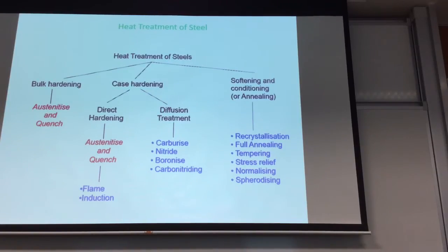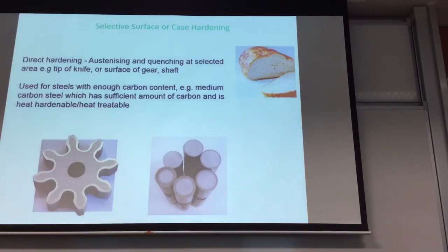These are for hardening. You can also see for softening, recrystallization. For example, hot working. What happens during hot working? As you said, the grains change. Actually, the formal term is that they recrystallize. Okay. You also have annealing. How do we achieve pearlite? Basically, it's through annealing. Okay.